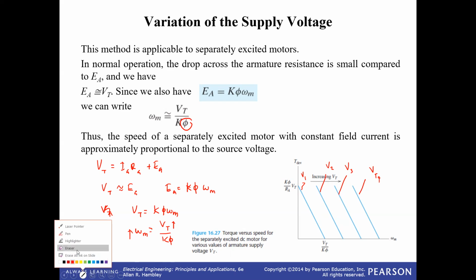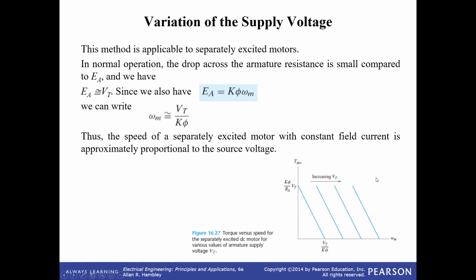This one is actually meaningful when you have the torque load. So this is the torque speed of the motor, and there are three types of torque load. We have a constant torque, like an elevator or lift, and we have a proportional one, and then we have the centrifugal or quadratic. Quadratic is usually referred to, for example, a fan and so on.